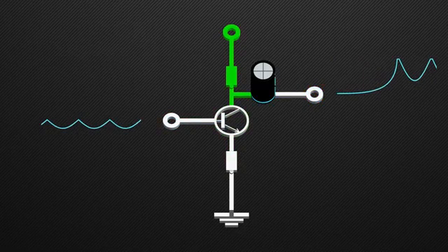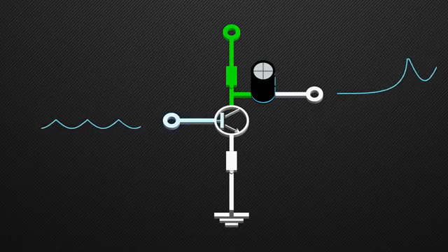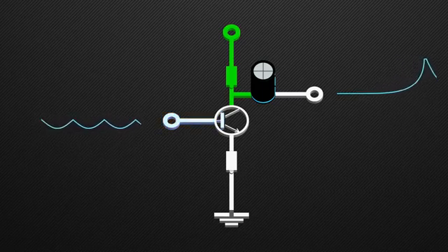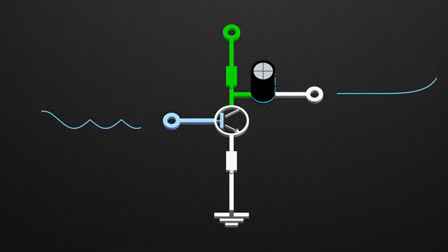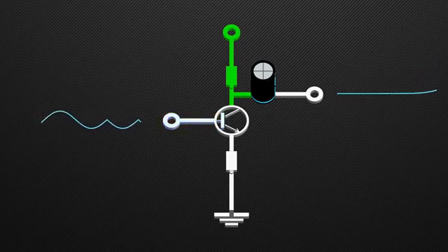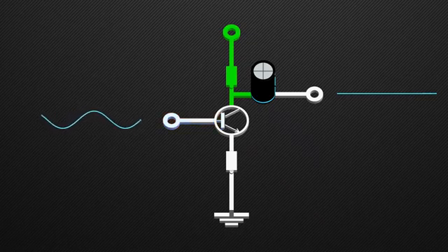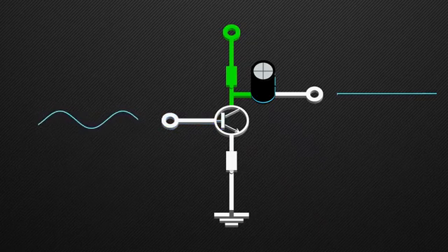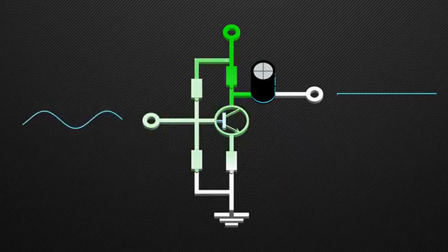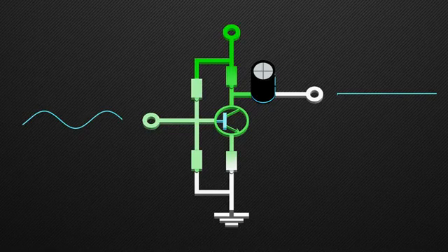You would know that a transistor requires 0.7 volts or above at the base to turn on. Thus, this circuit cannot amplify voltages below 0.7 volts. To make this actually work, we need to add a DC bias to the input signal, such that the input signal is always above 0.7 volts. And to do that, we add a voltage divider here. This will provide the required bias to the voltage of the signal. Now, a complete waveform of the signal can be obtained at the output.